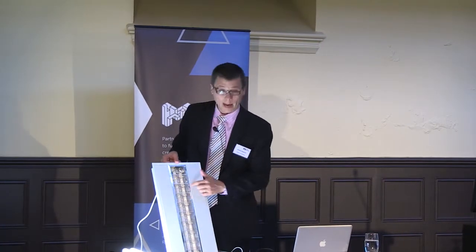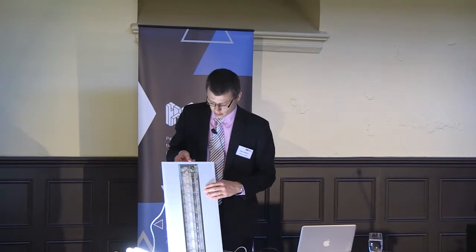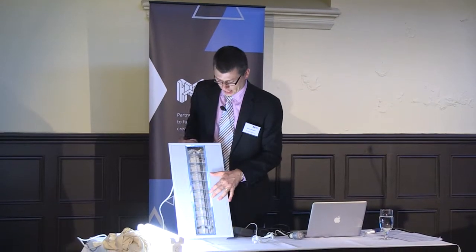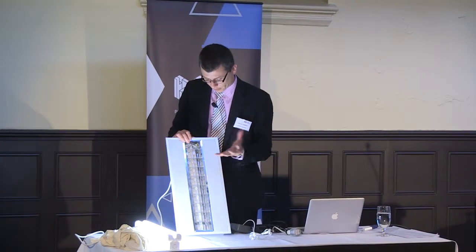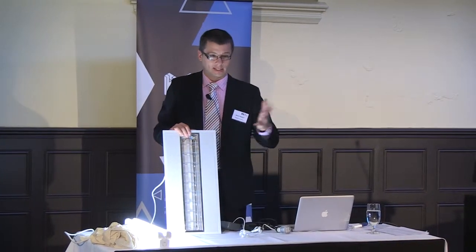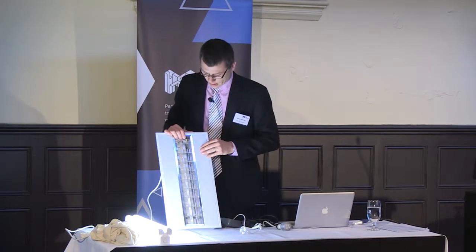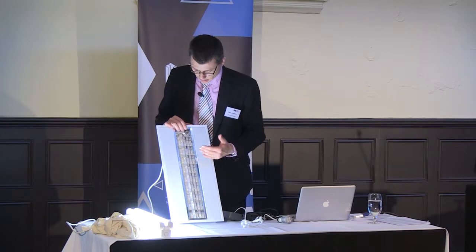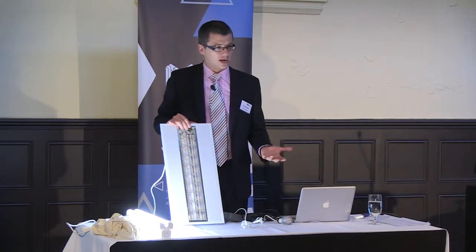So this is a luminaire, and you have a lamp in there, and that has an efficiency. You have a ballast, which is inside here, you can't see it, that has an impact on efficiency. And then you also have the light fitting, and its impact on efficiency is how much light comes out. Because the lamp emits light, how much of that gets out and is useful in our work environment, that photometric performance, we call it, because it's related to the light, and we call it a light output ratio.